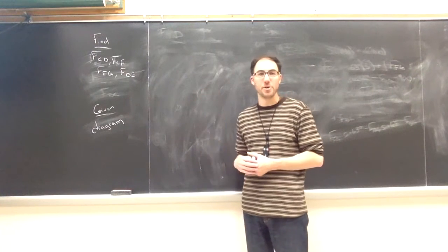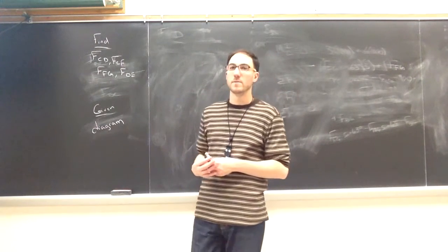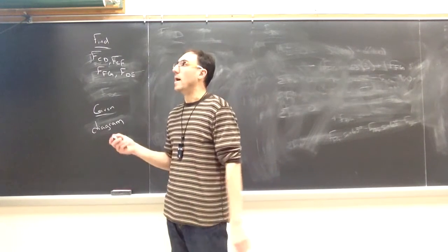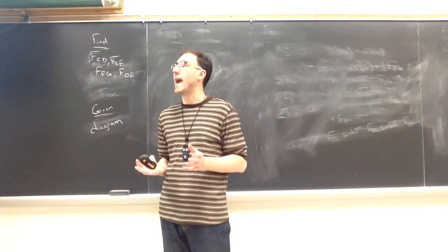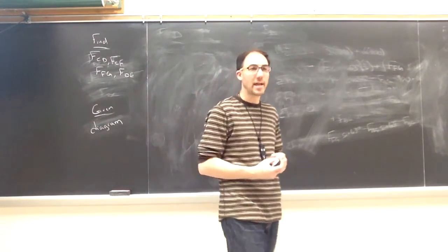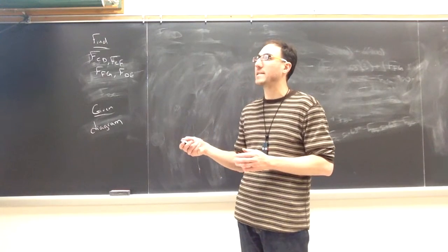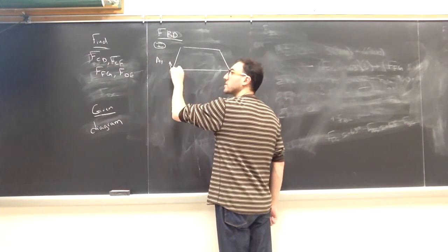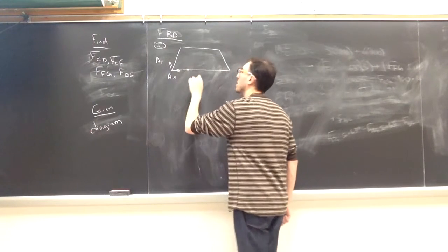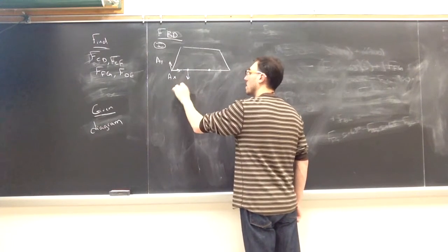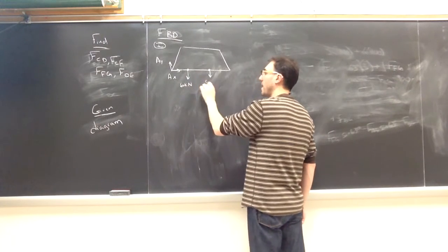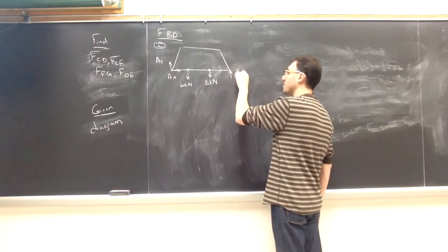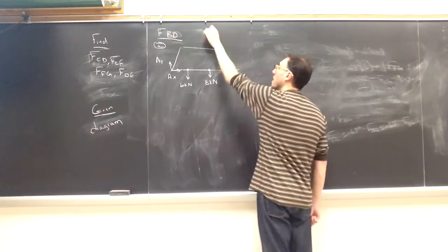So what's the first thing we should do in starting to solve this problem? Right. We can find our supports, our 3 reactions. We do want to draw the external free body diagram to find AX, AY, and EY. At A, I have that AY and AX. I have 2 applied loads of 6 and 8 kilonewtons. And then at E, I have just that upward force, EY.